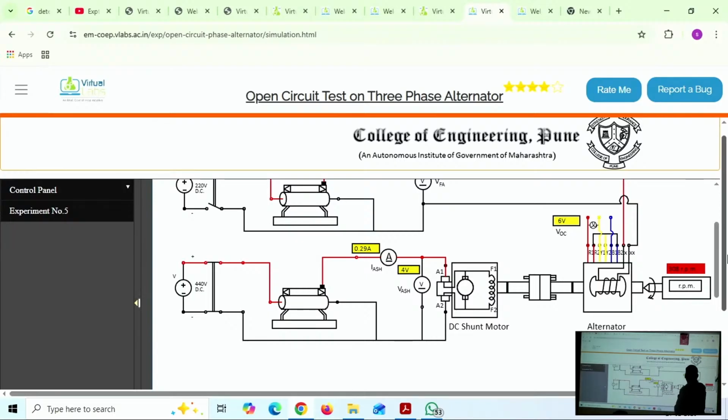That's it. Next, we will increase this up to 1500. Okay, assume 2-3 steps. We should take care of not only speed. What else is to be taken care of? We are changing currents here. Voltages we may increase beyond the rated on open circuit, but currents, in the entire electrical engineering, should be taken care of. Every time we say short circuiting, currents, short circuiting collapses everything.